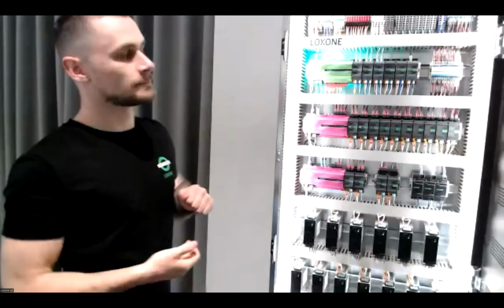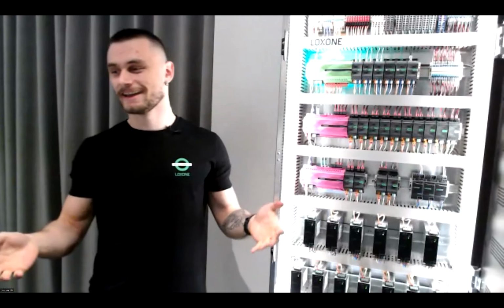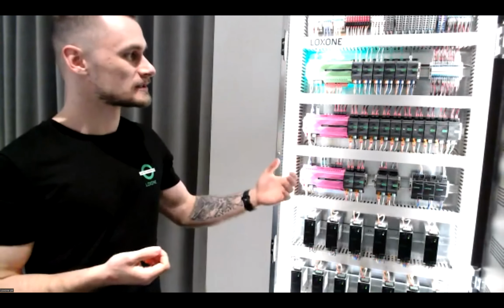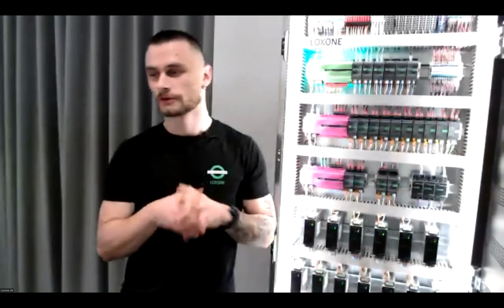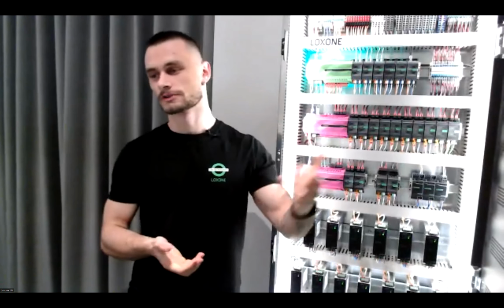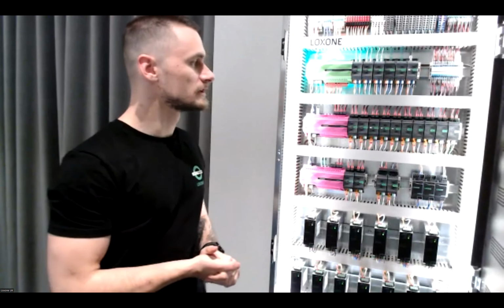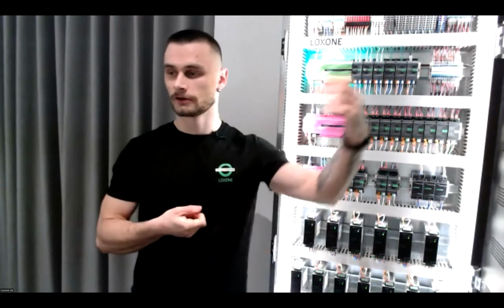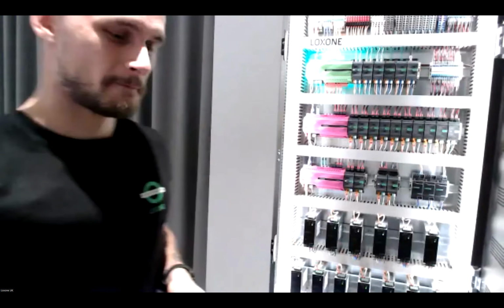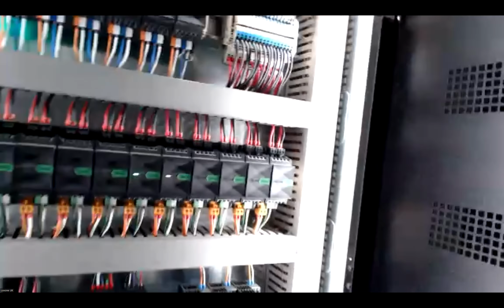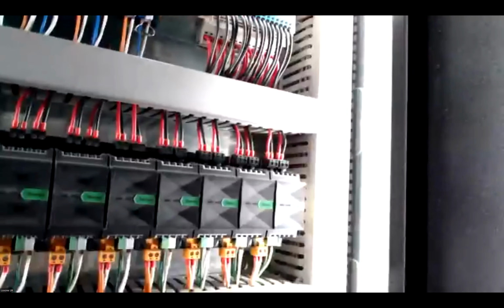Now, something else when it comes to terminal blocks, and that might be more me than anyone else. However, when it comes to speakers, you always want to make sure you have a nice quality cable. So usually low oxygen copper, and you want to make sure that you have thick enough cable depending on the distance between the amplifier and the speaker itself. And also you want to make sure it's uninterrupted. So because of this, I would actually advise for us to do something else.